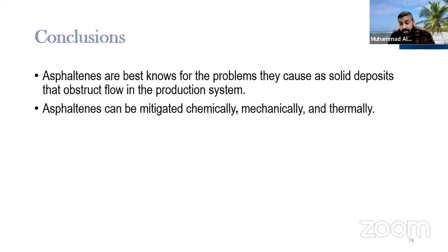It definitely creates problems for artificial lift systems, because they will choke down. There will be a lot of friction, and friction will cause wear and tear and heat up everything. So asphaltene is a big problem for artificial lift systems. You have to design these systems specially for asphaltenic wells. This is another good research topic you can do in your graduation project.